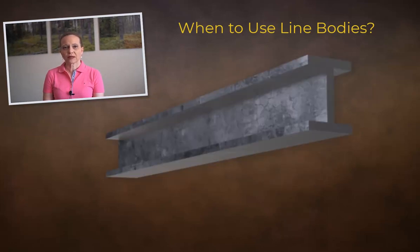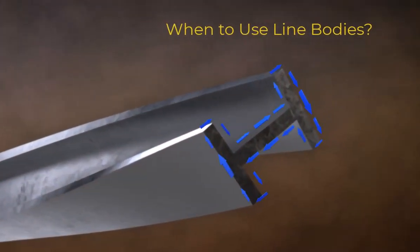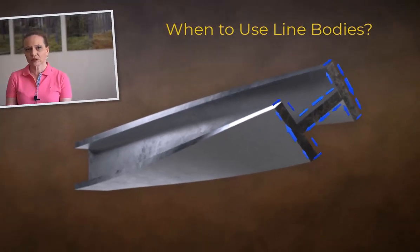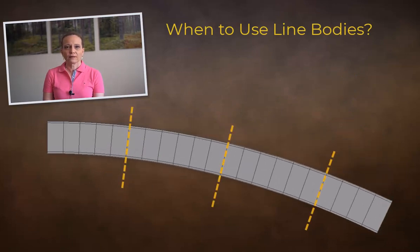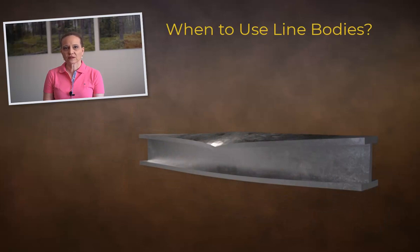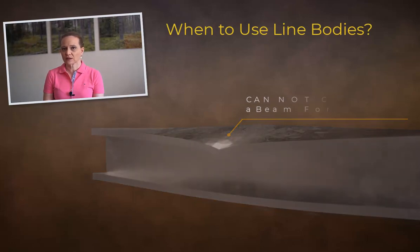If a torsion load is applied, the beam will twist and generate shear stresses. Here we can see one such example of the development of a shear stress from a torsional load. Keep in mind that the planar sections of a beam remain planar, and deformations and stresses in the plane of the section are not considered as part of the formulation. So, while we can capture the overall response of a beam-like structure accurately with beam elements, highly localized deformation can't be captured with the beam formulation. For such situations of very localized behavior, consider modeling the region of a structure with a solid model or using a beam-to-solid submodeling approach.